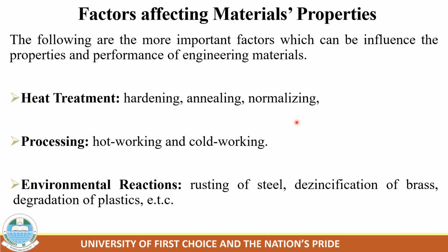So brass is an alloy of copper and zinc. In a situation whereby you place your brass outside in an environment that is too rusty, too corrosive, definitely the zinc will get out of the brass, it will react with the environment, because the reaction rate of zinc is more than copper. So the zinc can easily react with the environment and leave the copper hollow. So that is the dezincification of brass.